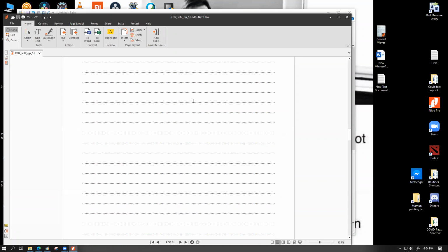Point 2, always prefer to use a ruler where you're supposed to use a ruler. Unless you are a very good drawing specialist who can draw straight lines freehand, and they actually appear to be straight lines, be my guest, not a big deal, but rulers are supposed to be used. And the other thing is that don't draw your equipment setups floating in thin air. In all appropriate cases, you have to show clamps, rulers, set squares, and if you require spirit levels in some cases, you preferably show those on your figures.